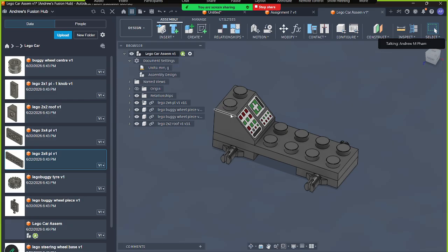So in this case, we're just going to do a wheel and tire sub-assembly, right? We want this to be separate because it'll make our life easier. We can create one sub-assembly with a fully constrained wheel and tire, and then insert it into our main assembly 4 times without having to reconstrain the tire and the wheel. So to do that, I'm going to create another assembly.